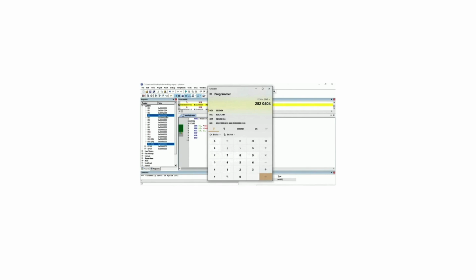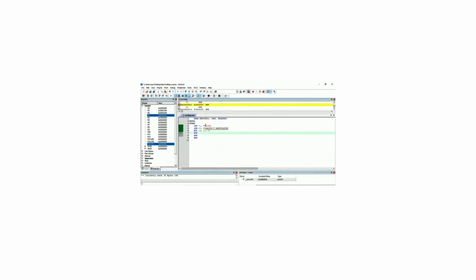This is how we write the program to multiply two 16-bit numbers, and the result is stored in another register, R3. One can change the values. To change the values, we need to exit from the debug session. We click on the Stop Debug Session icon.